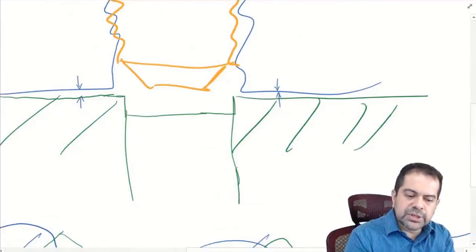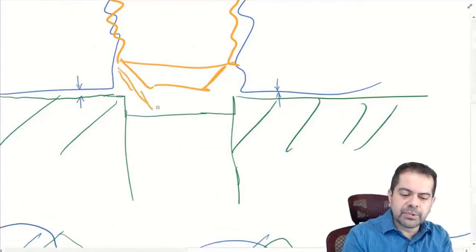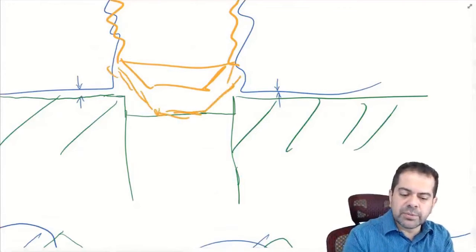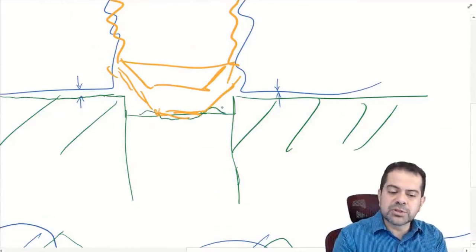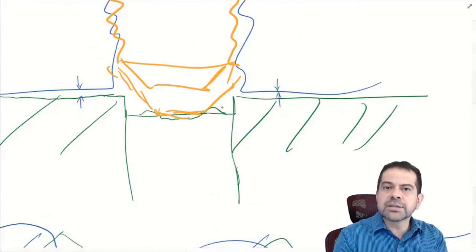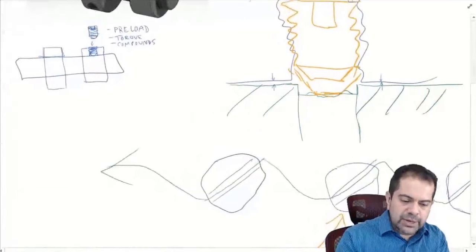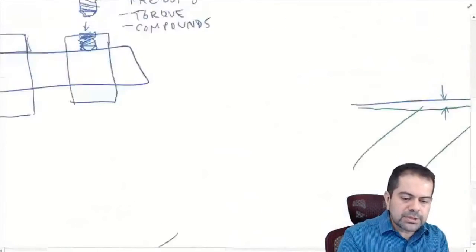So in that step now, the set screw would obviously go in deeper, and it would still do the same thing. It would still deform the material, but now the deformation is out of the way. If you want to remove the collar, you back it out and nothing is affected, and you're able to easily slide the collar off. Okay, so that's one issue. Now, another issue, if we look at a side view, let's take the sketch here.